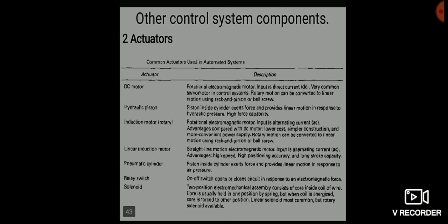They include AC or DC motors of various kinds, stepper motors, and solenoids. Electrical actuators include both linear devices and rotational devices. Hydraulic actuators use hydraulic fluid to amplify the controller command signals. The available devices provide both linear and rotational motion. Hydraulic actuators are often specified when large forces are required.